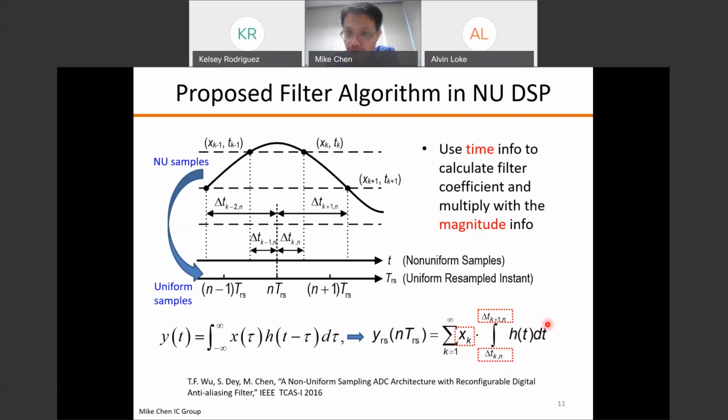But just to let you know, once you know the time, you have this filter response that you're trying to achieve. You can actually pre-compute this. If you have been working on the DSP part, there are pre-computing circuitries that you can potentially use. So you can pre-compute the result, and based on the time interval, you can read out that coefficient. So that's basically it, right?